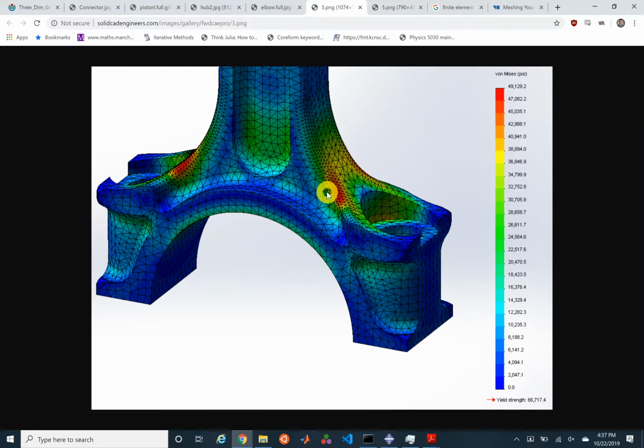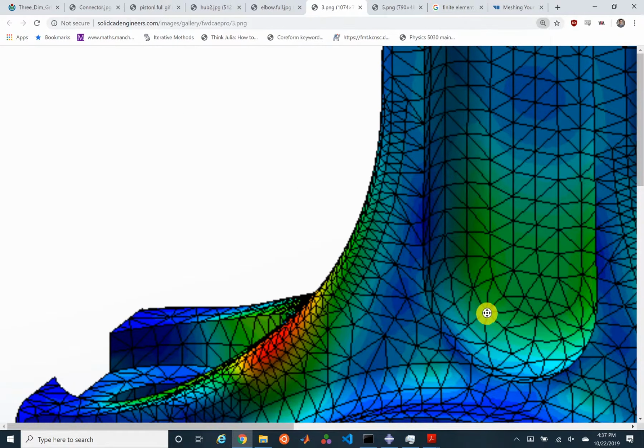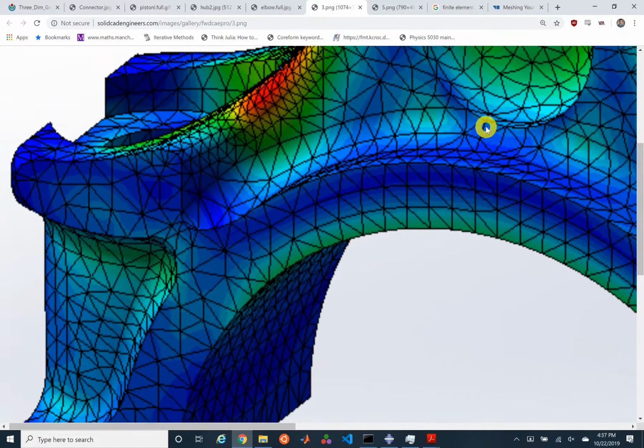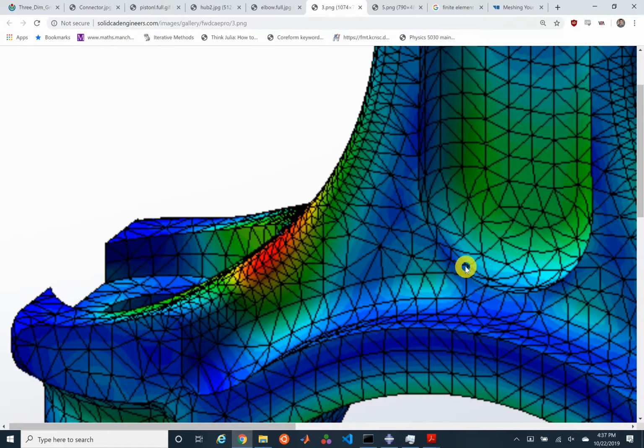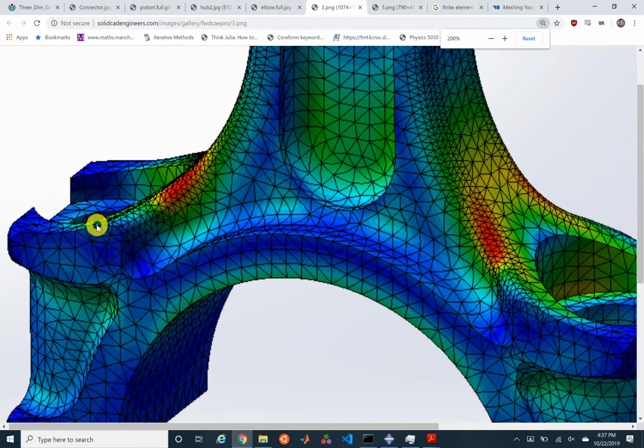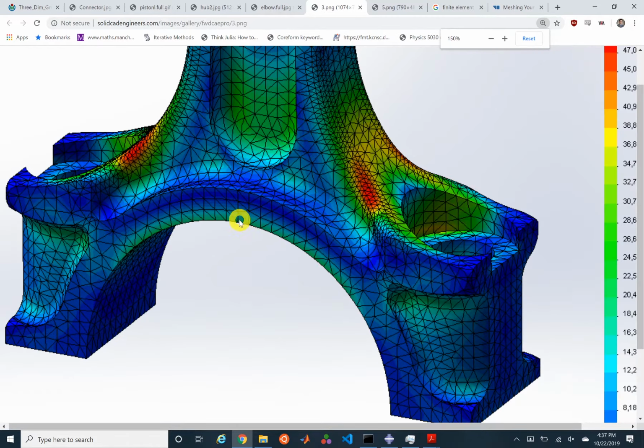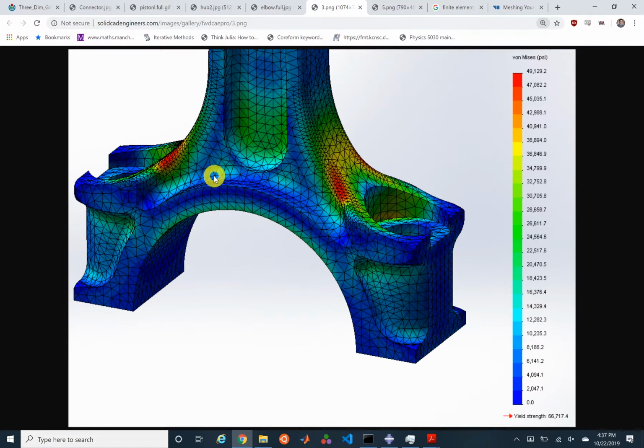And then just to contrast it, here we see a high degree tetrahedral mesh. The nice thing with tetrahedral meshes is that they can be fairly easily adaptively refined in certain regions. Here we can see, though it may be difficult to note, that if we zoom in, we might be able to see that some of these edges on these triangular faces of the tets appear to be curved, and so they're a higher degree tetrahedral mesh. But there are cases where these elements are desired.